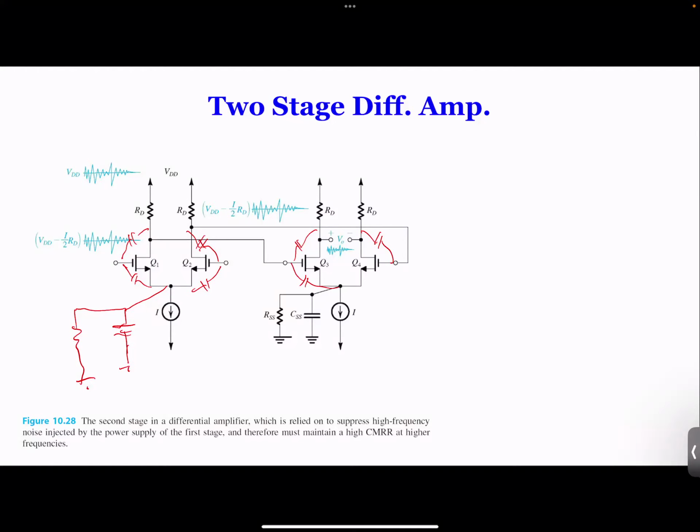So here, which means at this node, if you measure it, oh, the other thing I forgot to explain. When you measure DC voltage, right? You see a DC 5 volts and you keep increasing the range, you increase the scale, you're going to see it. But if the scale is too big, it runs out of your screen, you cannot see it, right? Then use AC. Your oscilloscope has a DC measurement, AC measurement. Use AC measurement to filter out the DC. Okay, the DC is gone. You only look at AC. Now you can increase your time scale, decrease your time scale, and increase your amplitude scale, and you can see the noise coming. So if you measure it over here, you're going to see the noise.